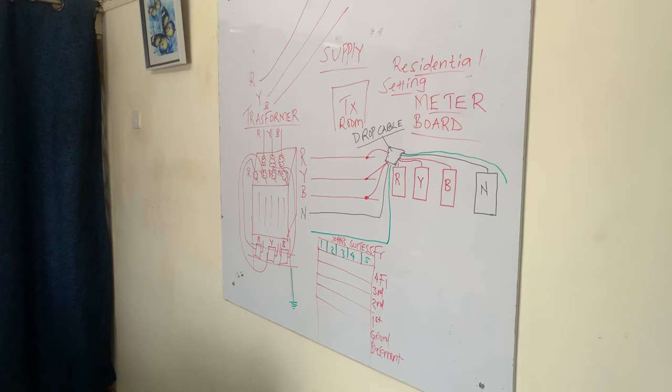If you have not balanced your load, then you may cause issues with their power distribution, or probably cause issues with the transformer that is supplying you with power, especially if that transformer is serving several people, not only you, or probably not only your client.